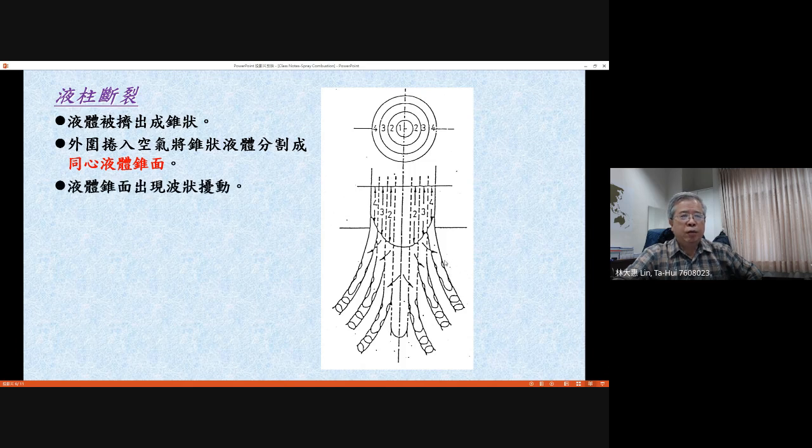And those kinds of wave disturbance, just like a wave disturbance on a small liquid jet, will have increased intensity to break up the liquid sheet into ligaments. Here you can see a cross section of one liquid ligament. Ligament means just like a donut. This is a donut, but if you take a cross section, then you can just see the cross section of the donut.